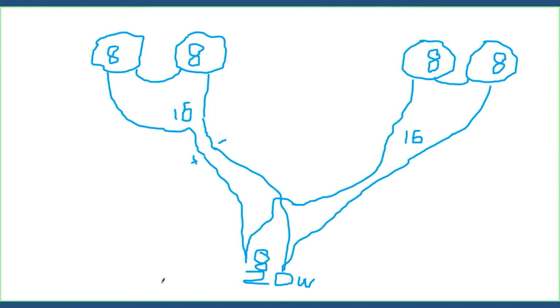We still have our 20 amp amplifier. It still sees 8 ohms as a load, but what does it do now? It's moving 4 times the amount of air with the same amplifier. And each speaker, because of the loading, the way we've wired this up, is going to flex as much as the one speaker by itself. So each speaker is going to move the same amount of air as that one by itself, but now we've got 4 speakers doing it. So our noise level just quadrupled.